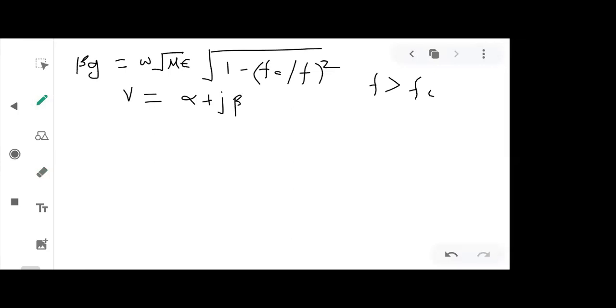Okay, since we are dealing with a waveguide, I will write it as alpha g, and here is beta g, and this will be gamma g. So if the solution tells you that beta is real in nature, it means that in that medium the wave can propagate. But beta g is already an imaginary quantity, and if it turns imaginary again, imaginary into imaginary will become real in nature. It means that in that particular medium the wave cannot propagate.